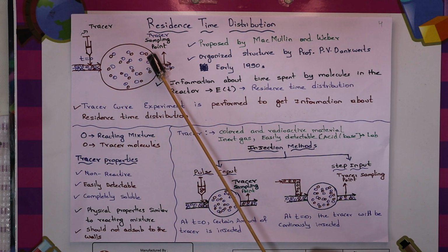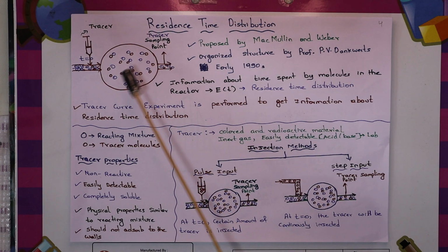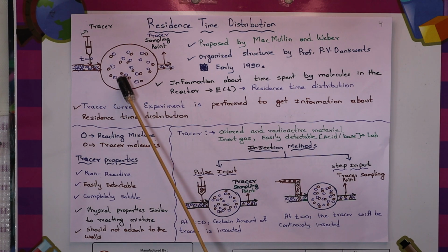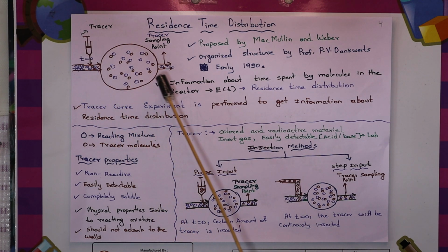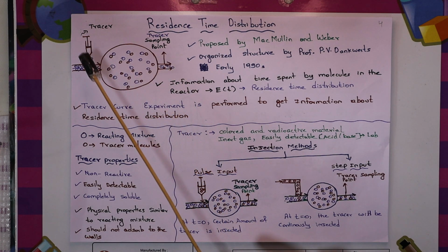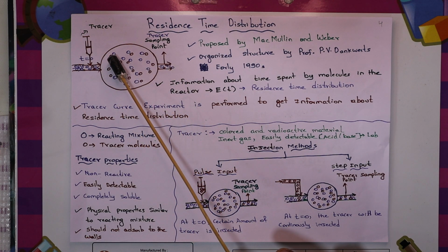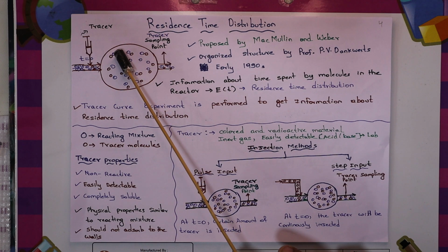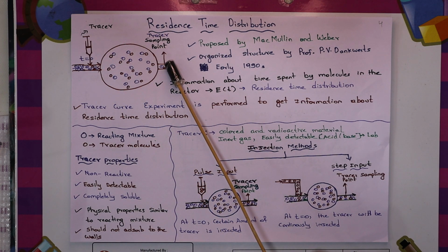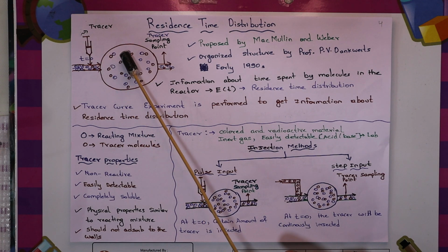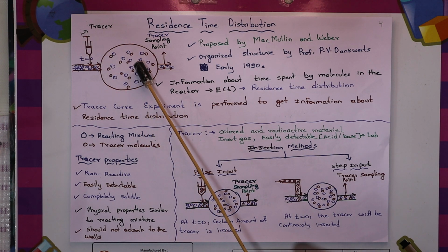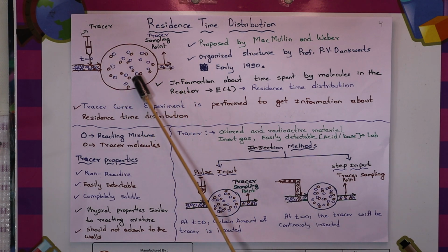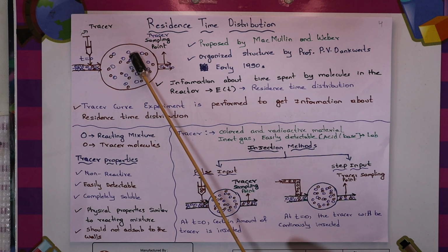You can observe, I represent the non-ideal reactor with a circle where some reactants go inside and some product comes outside. The blue circles represent the regular reactants going in and product coming out. The red circles are my tracer. A tracer is a substance which we can detect at the outlet. These tracer molecules travel the path along with the regular molecules, so by detecting the tracer at the outlet we get information about how the other molecules spend time in the reactor.